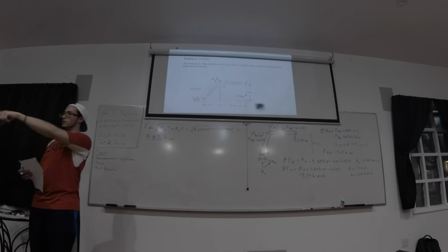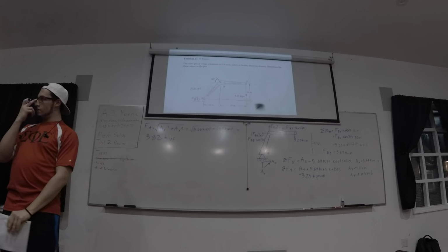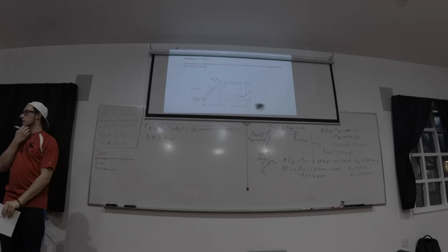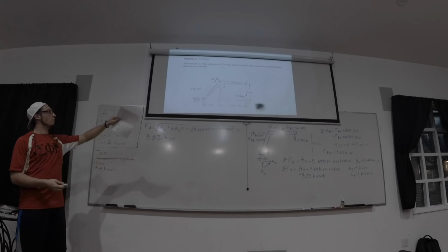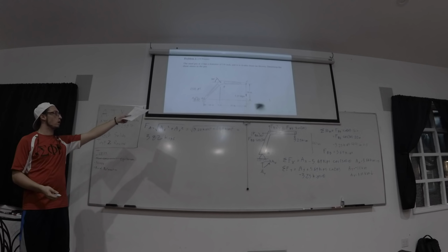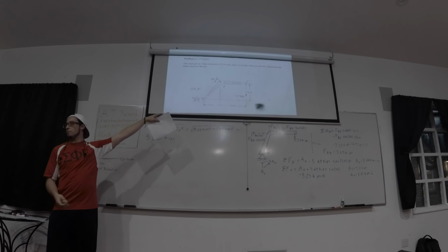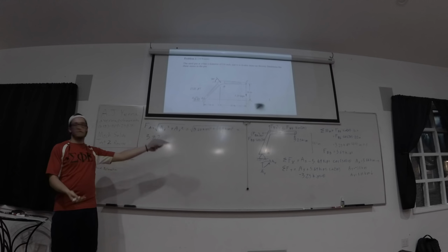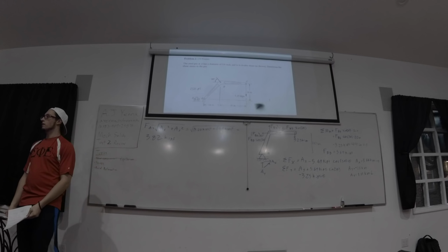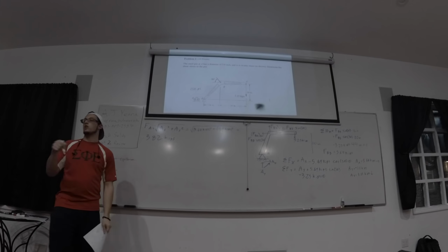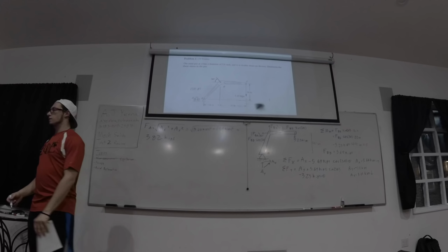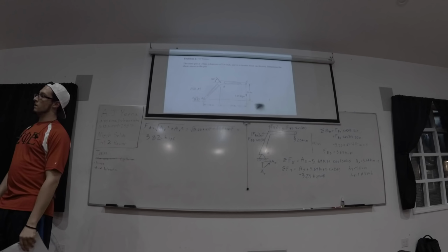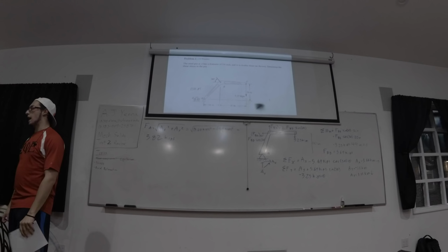Any more questions for people on this? Yes. So the force you use in the equation with the force on area, it's always the force on the pin, so it's always going to be that force? Yes, exactly. In this case we have a pin at A, so we wanted the force at A. If it was at C, it would be the force at C, whatever that point is. And then you need the cross-sectional area of that same point. You can use like 1/4. Exactly, yeah.